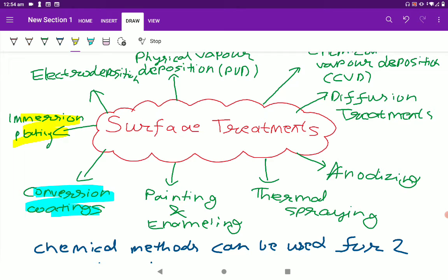The most common one is zinc deposition. A steel component is dipped in a bath of liquid zinc, and then we have diffusion of zinc on the surface layer, which produces an external layer of zinc-iron intermetallics and zinc metal. So the surface modification or external coating is obtained by adding atom by atom to the original surface.